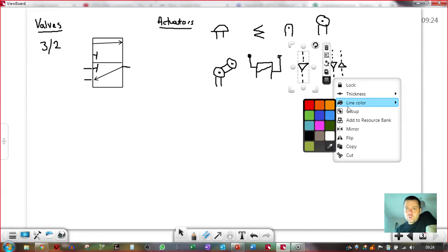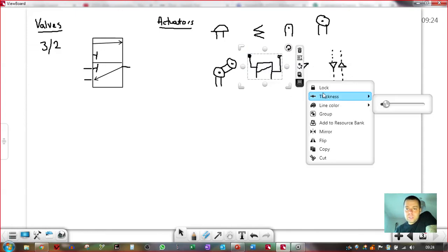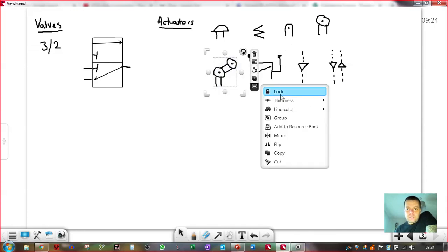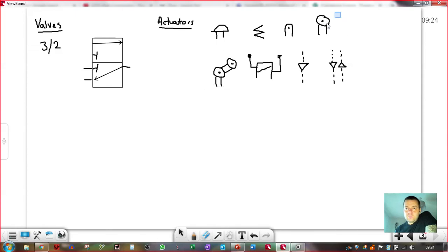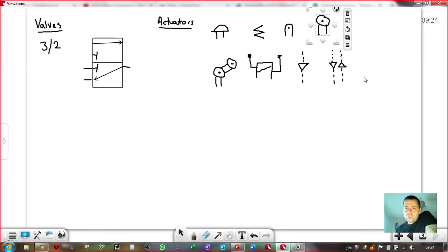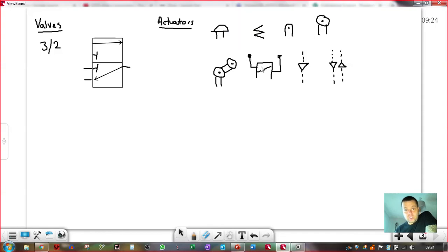So we can use diaphragms, we can use wee tiny air leaks called air bleeds to detect or to trigger valves. The plunger, the roller and the roller trip, these three that I'm just grouping just now, they are the ones that allow automatic circuits to operate as well as solenoids, obviously.